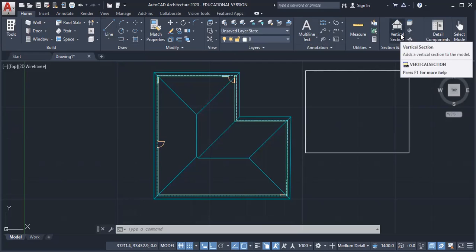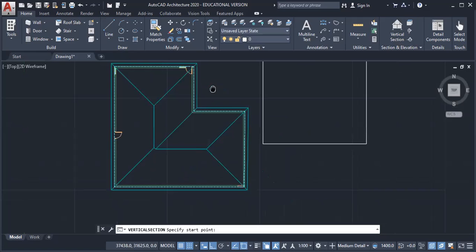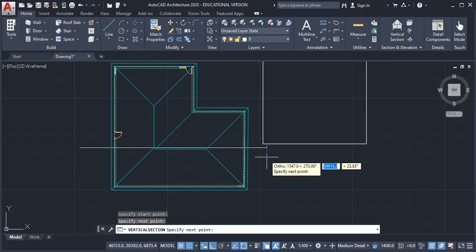Here you can quickly cut a sectional elevation, and you can determine where you want to start this building right here. Let me start that over. Click on sectional elevation, left click there, left click here, then enter. And I bring this there.